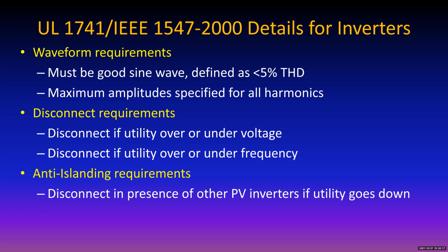And the reason that the inverter output waveform is not perfect is because it has a little glitch when it goes through 0. And that's the synchronizing glitch. And if there is nothing to synchronize it, the inverters are programmed such that the current frequency drifts away from the 60 hertz. And when that frequency drifts away, within about 2 seconds, the inverter realizes that there's nothing there to synchronize the signal, and it shuts down.